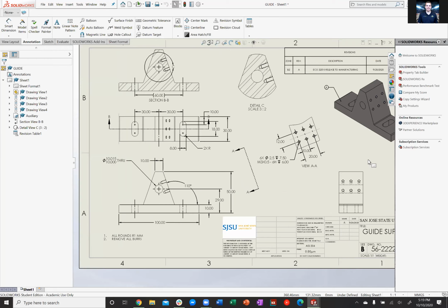Consider that when the part is sent to a manufacturer, if you don't tell them that the drawing is different from the part, just for us specifically, not in a production part environment, but for sponsored parts, try to make your CAD exactly the same as the drawing, except for the threads. That way it is easy for the programmer to program, and then they look at the drawing and can just select the tool for the threads and make minimal adjustments.